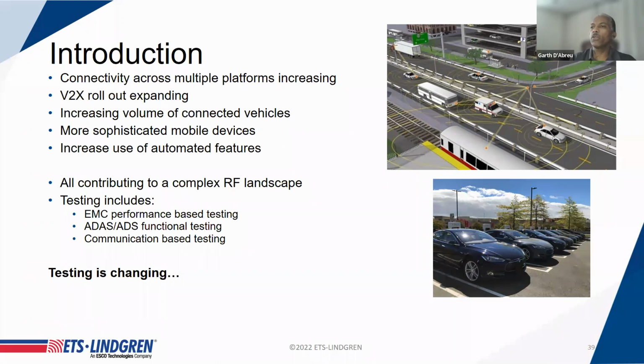And what I mean by that is the design of the radio, the transmit antenna, the over-the-air portion of the link, how much loss they expect to have over whatever minimum and maximum communication length they expect to see. And then on the other side, the receive antenna and the receiver, the receive radio that is going to interpret that received signal. That communication link has to be suitable for its intended function. So manufacturers have to come up with some way of demonstrating that, again, under controlled environments. And this is one of the areas where we're seeing increased interest in providing facilities to satisfy these tests.